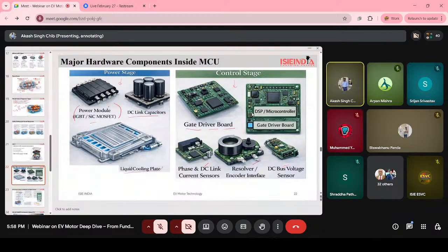You can see here, these are the MOSFETs. Basically, the MOSFET is for the switching, like I have told. The Hall sensor gives the direction to the controller part, and they are doing the switching. It converts direct current into high frequency alternating current, and these devices switch thousands of times per second. Like, if a motor is moving at 5,000 RPM.